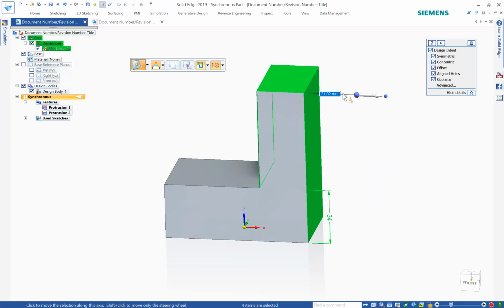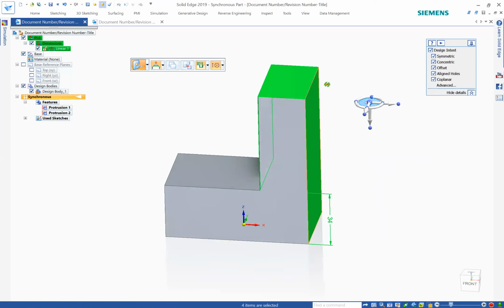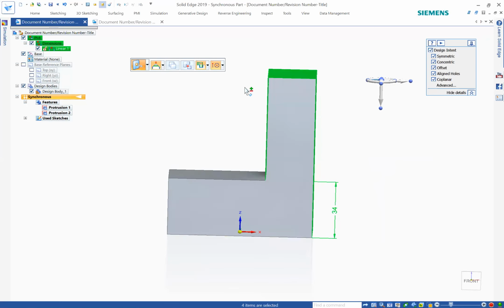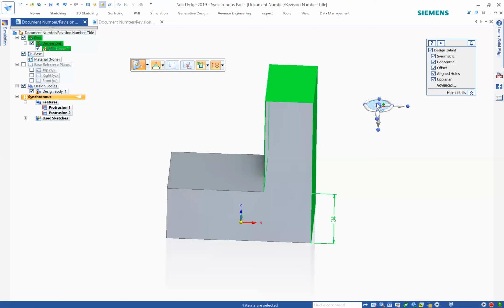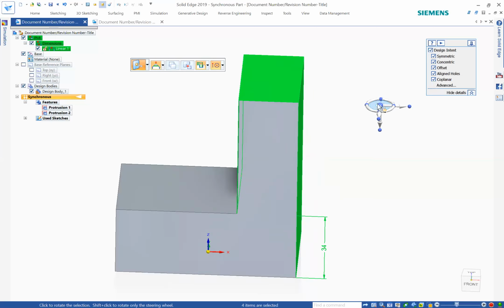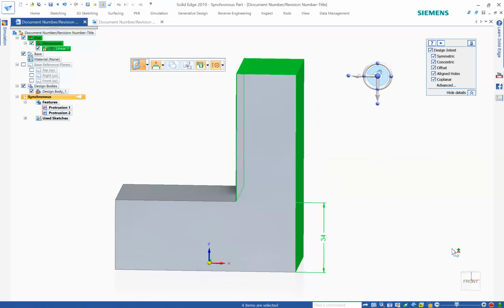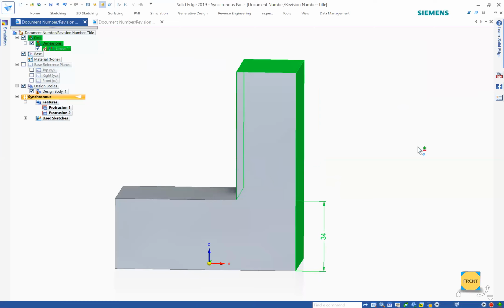What it does is it aligns the steering wheel, but it translates it wherever you want it to move. So I want to move it right here a little bit, and then I want to be able to rotate this from either this direction or this direction. But the steering wheel is not in the right orientation. So I'm going to press shift and press in the middle of the steering wheel. You see this little area? Press it right there, and it changes the orientation.